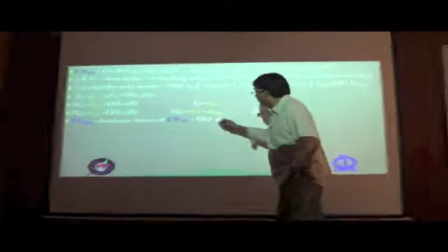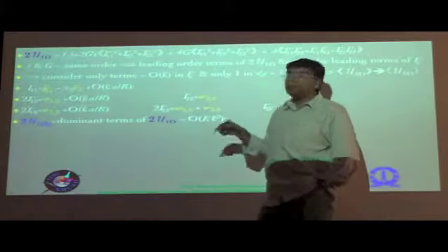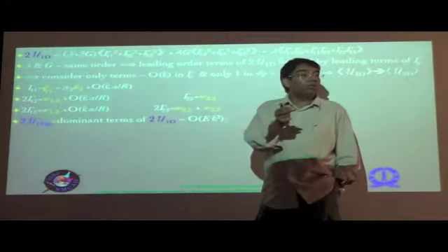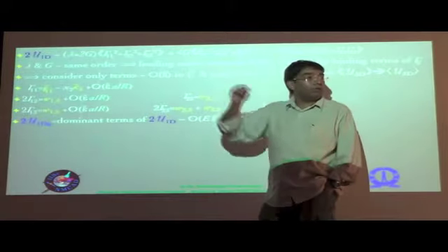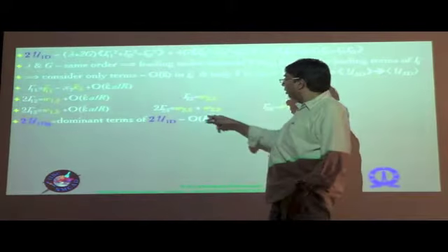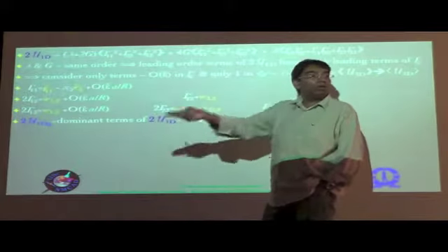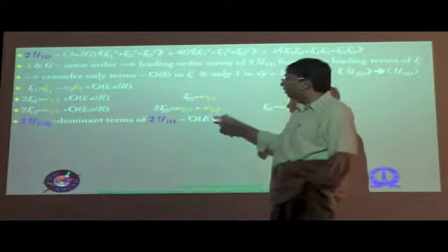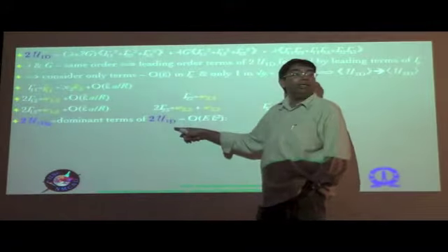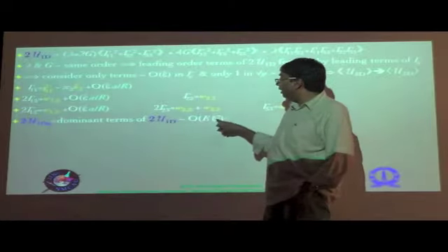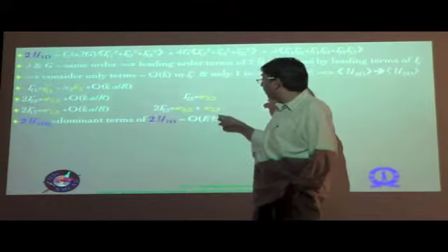Right. So of course the material constants are all, let's say, of the order of E. That is, the order of magnitude of lambda is E, the order of magnitude of G is E. Everything is in terms of lambda and G, the Lamé parameters now. And then there is one material parameter which comes, and two contributions from the strains, which are basically both of the order of epsilon hat. So the contribution of all the leading terms of U1D would be E times epsilon hat squared. Okay. So that's basically at the 3D level.